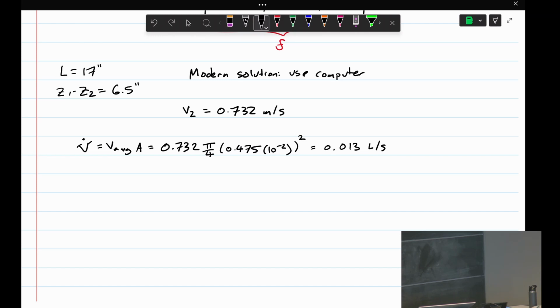By the way, we did assume this to be turbulent, right? If you verify with that velocity, you actually get turbulent flow even at this very small diameter. Okay, what did you guys get? 38. 38, okay. So that was 500 milliliters of liquid. If you do 500 divided by 38, you get something like that in terms of liters per second. It's close. We'll probably have like a 10 to 20% error with the assumptions we made, but I hope this helped you understand the different assumptions that we're making in this problem.